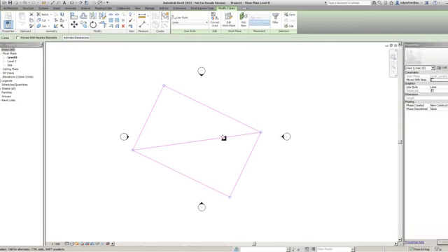Okay, now let's just say this geometry that I've got on my screen, I just want to correct it back up. I just want to horizontalize it, okay? I'm not even sure if horizontalize is a word, but it seems to be appropriate for what we're going to do just here. Now I'm just going to make it horizontal on my screen. Now in AutoCAD, basically you'd have to then do a rotate with a reference and pick some other points on one of the lines and bring it back up. What we do is this: we go rotate.